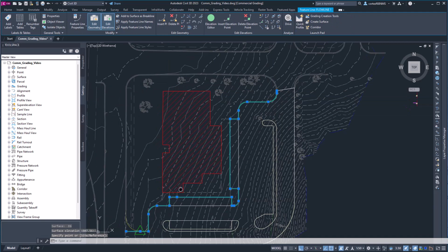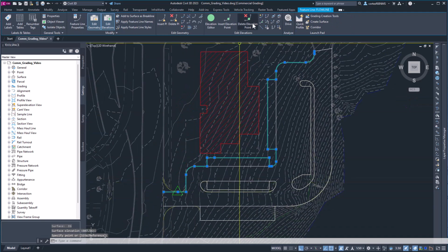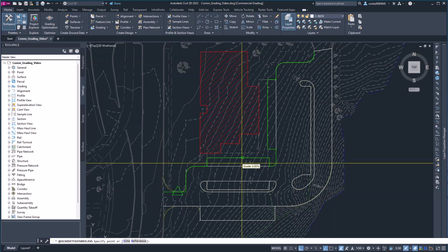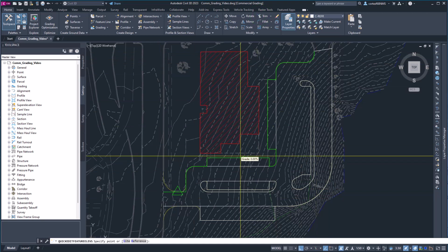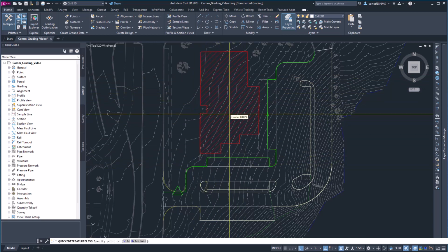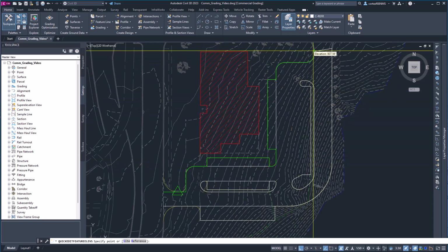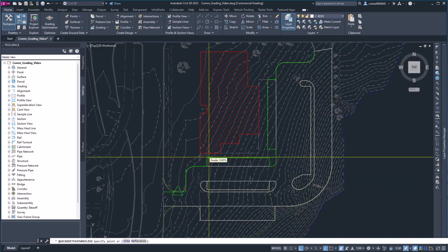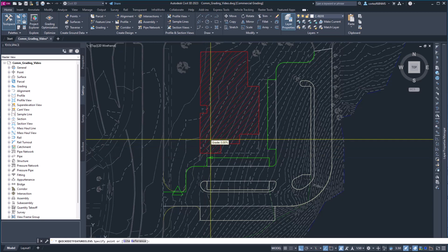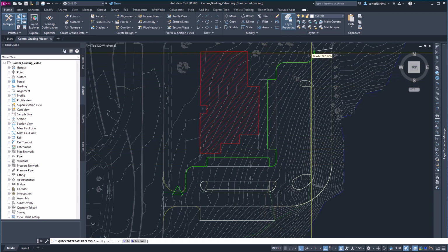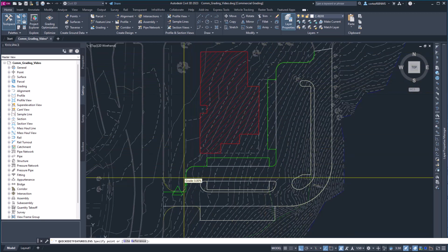And so we're at 807 on that side. We're at 818 on this side. So we've got 10 feet of fall through here. So more than likely, this building is going to be a little up in the air. And then we're probably going to have to dive down here, see what we're at in this spot, and set our building elevation. This guy's going to want to be flat, and then we're going to dive back down and see if we can hit existing ground.